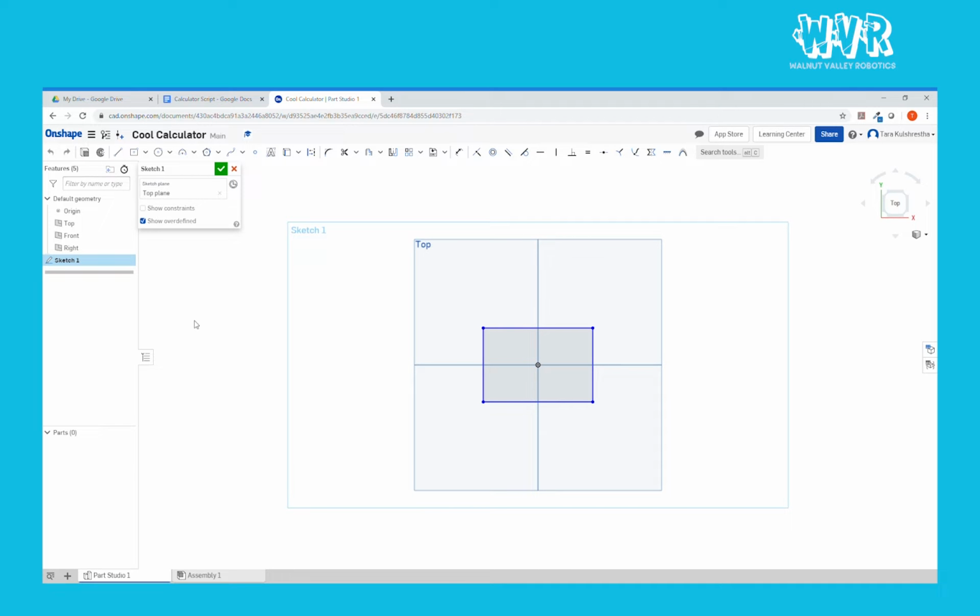I'm going to start dimensioning with the rectangle's height. Click on the Dimension tool at the top. Click on the left side of the rectangle, then drag out until your dimension is in a suitable location. Click down, then define the length of what you have selected. This one is 4.4 inches. Type 4.4 and hit Enter.